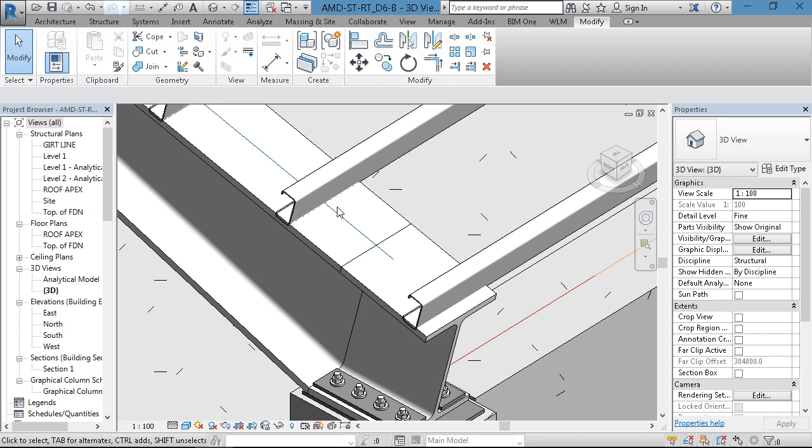Divide, you put divide slash, Control V, Enter. Yeah, okay. So you have 4. Click OK. So you have only 4, right? So you go back there and you change that spacing to 200. Okay. You change 200.